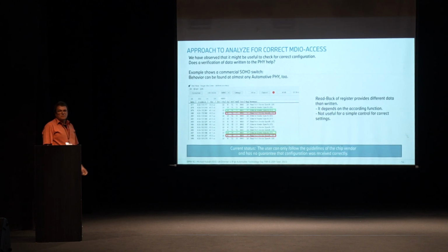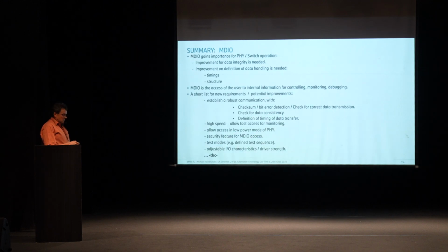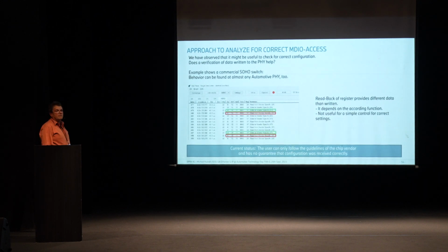Then there was the idea, oh, let's check if you have written the correct data by reading it back. This example was made on a normal file, it was a switch, and it shows that once you write the data and immediately read it back, there's no guarantee that you get the same value, because internal processes might have changed the value already. With this, you can only strictly follow the guidance of the chip maker to write data and hope that it's correct. You have no guarantee that this configuration is really the one you wanted to write, that it's received correctly, and that the device behaves the way you want.